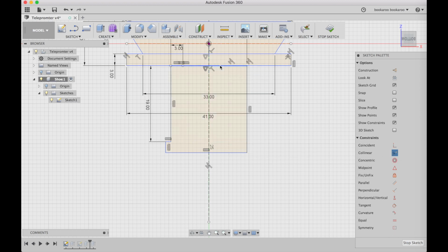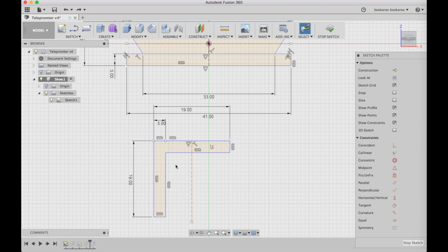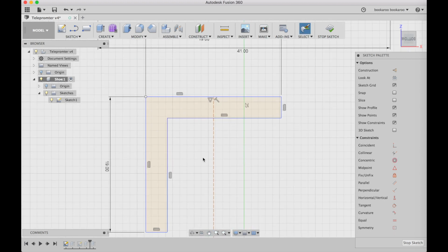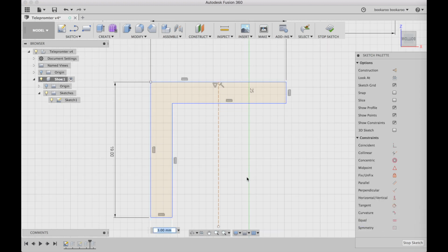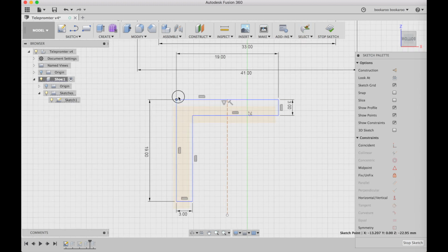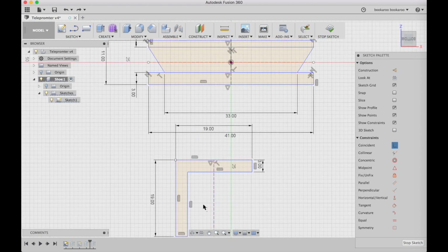and then matching the top, and it doesn't work because my first rectangles are not fully dimensioned, so I'm gonna try to remove. Okay, deleted the line, and then fully dimension everything, going the 3mm there, so that doesn't move when I move the part. Same thing here, 3mm, so everything is dimensioned. So I can now drag the part without it being distorted.